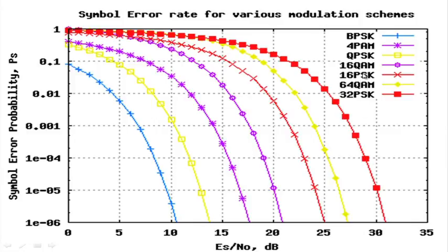With higher order PSK you get the advantage of spectrum efficiency. In one symbol period you can push more bits, that is the bandwidth advantage you get, but you have to give more power to reach the same BER. Now, normally in clear sky operation you are operating at a higher order, but because of the rain you have attenuation of this much, say 15 dB.